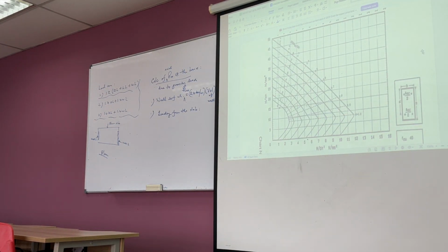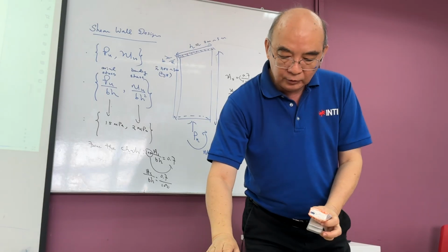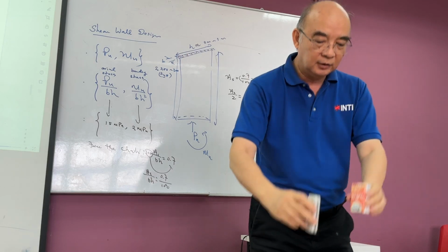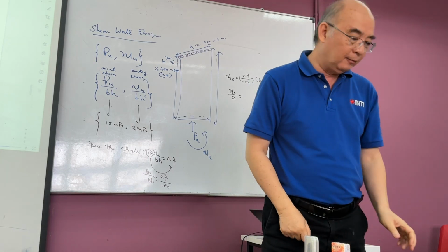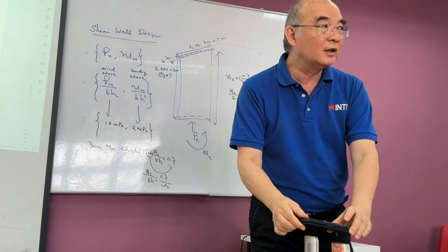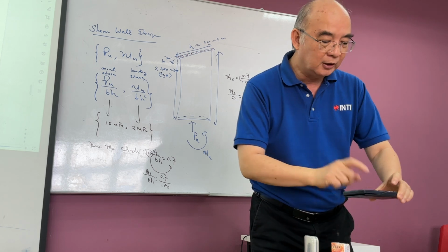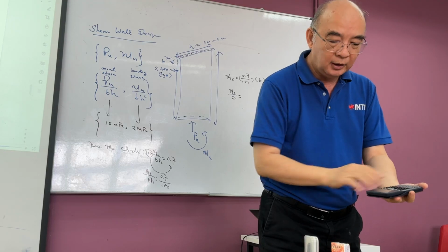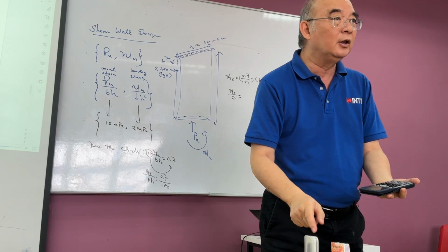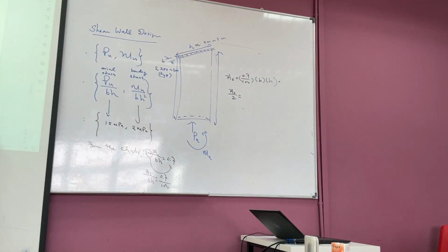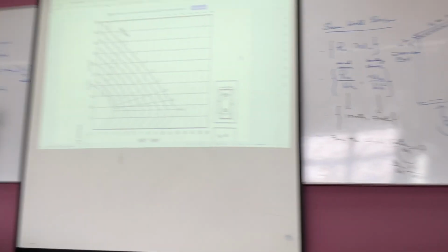Just like, let's say this is the wall. This is the wall. This is the wall. So they have the self-weight, right? Then I also have the slab sitting on the wall, right? So that is why the slab loading has to be transferred to the wall. So you need to account for that. Understand? So that is why the second item is loading from the slab.